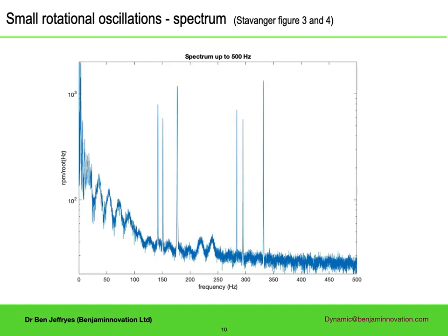But going out to the maximum bandwidth of the gyroscope, suddenly some really sharp resonances appear, at around 140 to 170 Hz and 280 to 350 Hz. In the actual data, the resonances above 250 Hz do not appear so large, but that is because the anti-alias filters started having an effect above 200 Hz, so I have attempted to remove their effect in this simulated data.